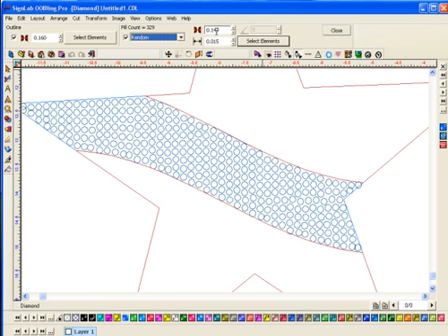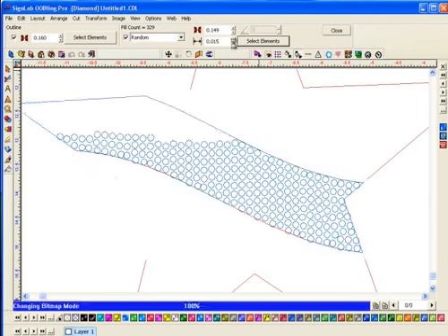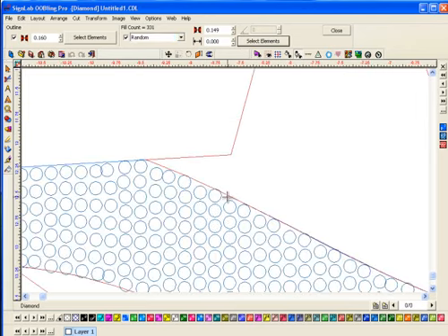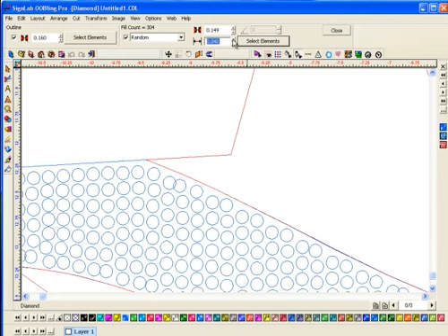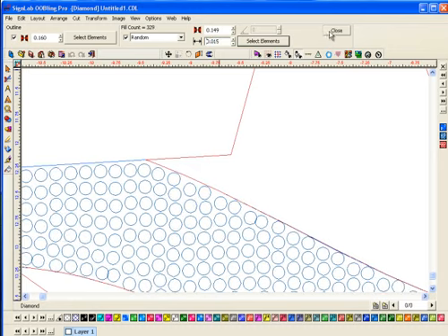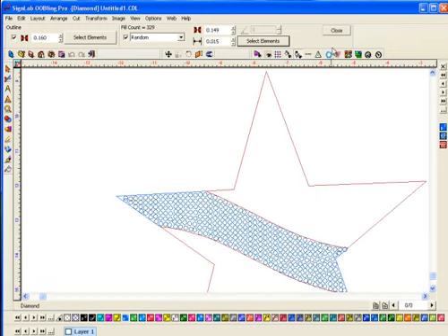And then this one up here will do the spacing between each element, and this will do how far away from the edge of the line. I did this one at 0.15 because when I lay these stones on the red section, I don't want them to overlap. So if I went down, you can see they get closer to the line here. As I increase this, it moves away from this line. So I had 0.15, which I thought was pretty good. So I'm going to back out of here and close that.